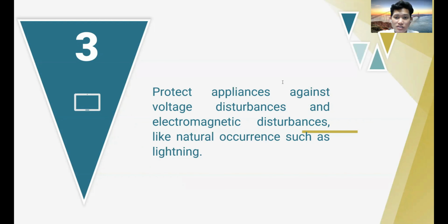As long as the currents flow in the earthing system and not in the electronic circuit, they will not do any damage. However, when earthing networks are not equipotential, such as when they are star connected to the earth electrode, the high frequency stray currents will flow wherever they can, including in control wires. This situation can cause equipment to be damaged or even destroyed.